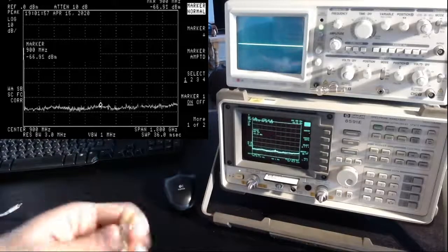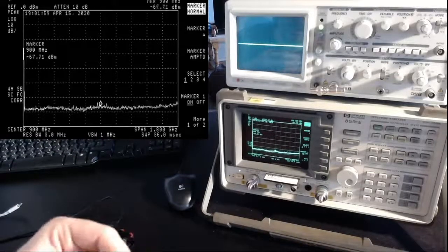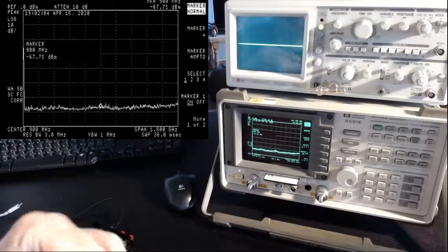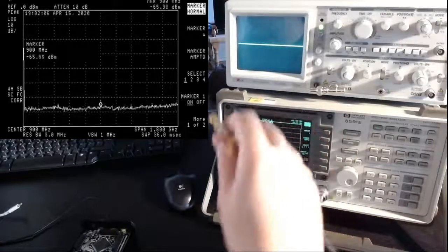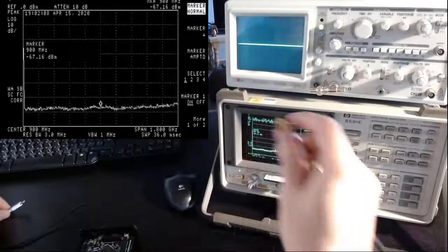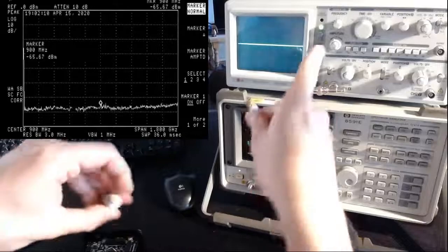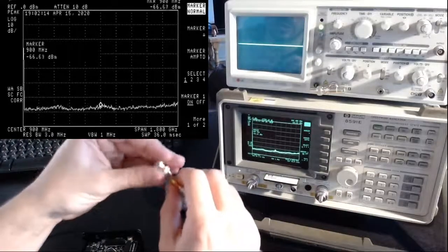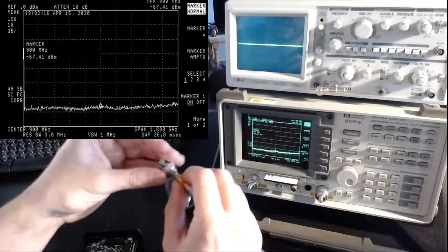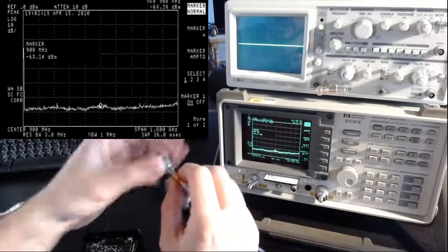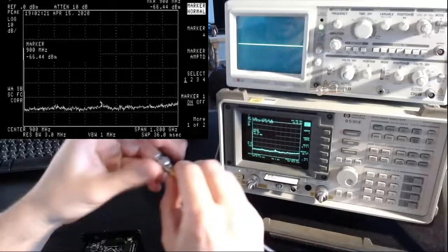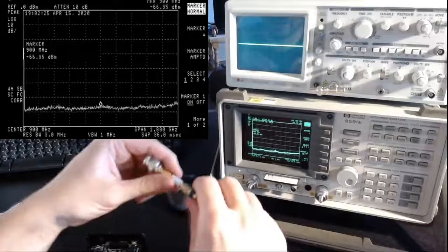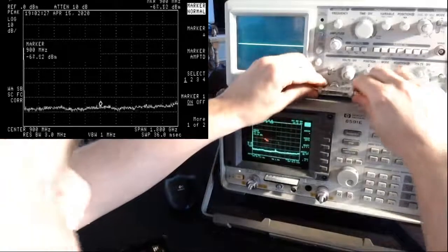I'm going to add this. And as a form of extra precaution, I'm going to attach first the output of the HackRF to my 20 megahertz bandwidth analog oscilloscope, just to make sure things are going as expected and we are getting the expected signal out there, not something weird. Again, I'm very careful. I want to protect my spectrum analyzer as much as possible.